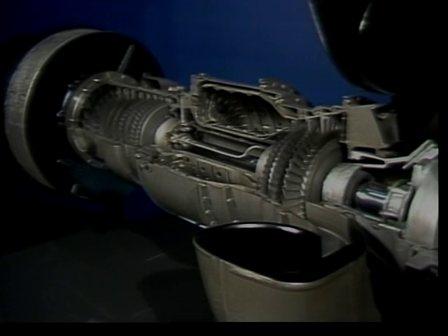The turbine engine uses heat and pressurized air to perform work. There are several properties of air which should be kept in mind in order to understand how air and heat are put to work. These properties explain how energy is converted from one form to another. The turbine is designed to take maximum advantage of energy conversion. We know that air consists of minute particles, invisible to the eye, called molecules.